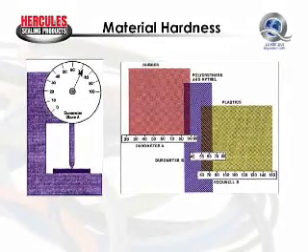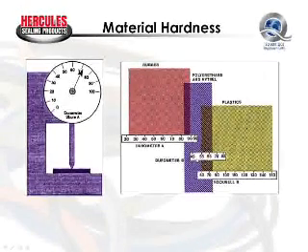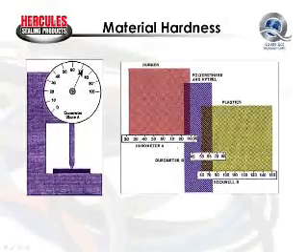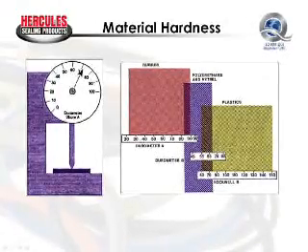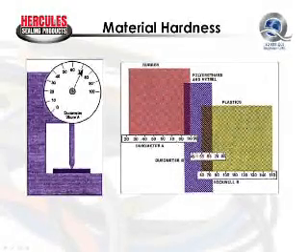So if you look at some U seals or some urethane seals, you may see some of them measured on the D scale, where it'll say 45 or 50. You may see some of them measured on the A scale, where it'll say 90 or 92 or 95. And some seals that are made up of two different urethane components may actually show two different ratings for the two different scales. So always remember that there's two different scales for measuring the hardness of the seals.